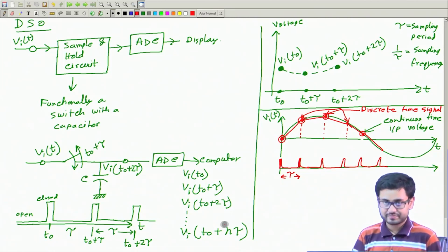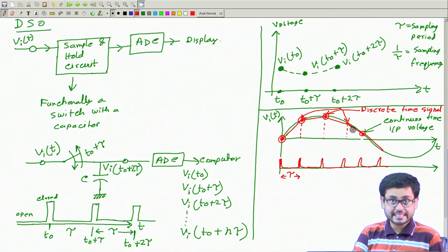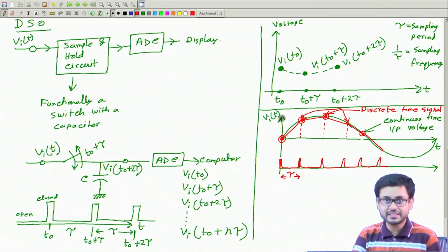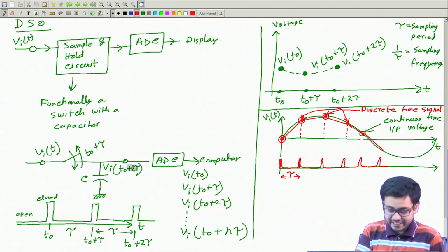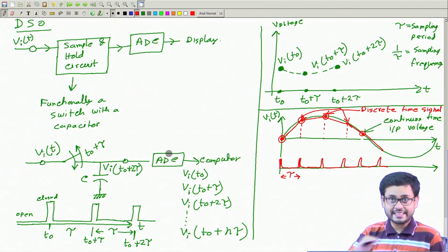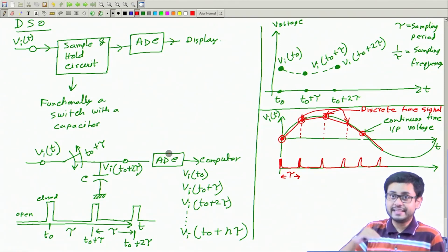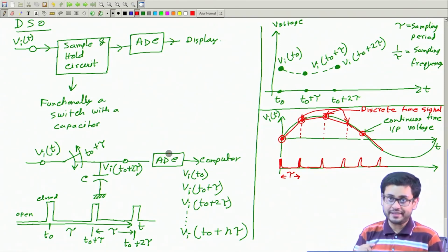There is another important fact. That fact is that the measured value is not just discrete in time, it will also be discrete in the measured value. This is an ADC, an analog to digital converter, which is measuring this voltage. And when an ADC measures a voltage, it discretizes or divides the range of voltage into small quanta, right?